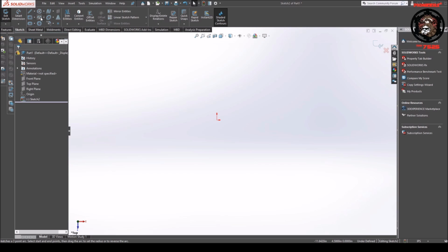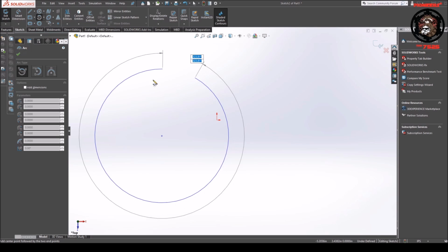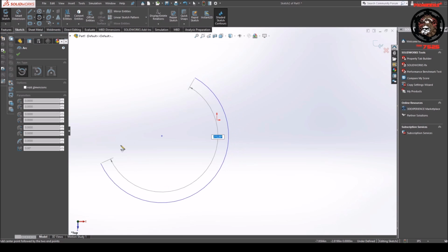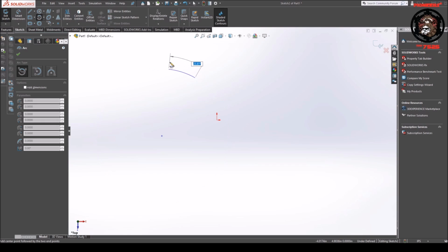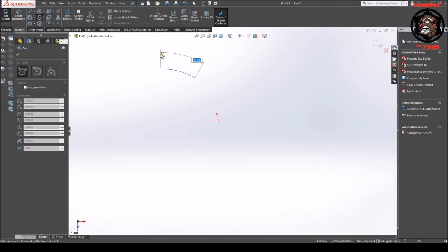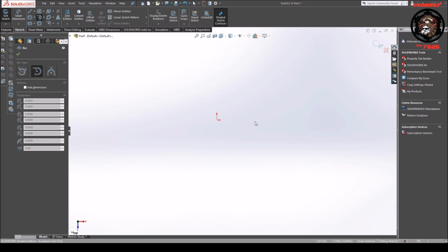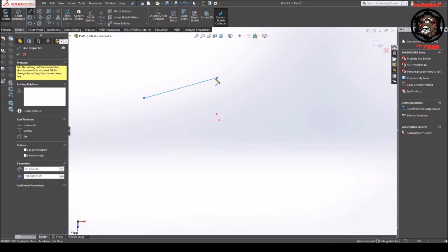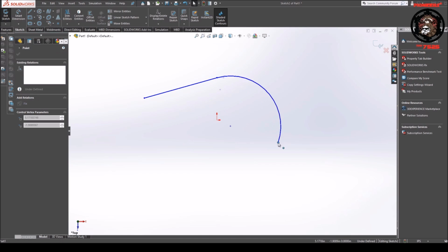Next are your arcs. We have center point arcs, your standard. You can create center point arcs like that. I believe the direction is always clockwise. So, oh, there we go. Never mind, you have to work counterclockwise. So you just have to fiddle with it to get it working. And we have tangent circles as well, but I need a line. So say I have a line here, and we can create a tangent from that.